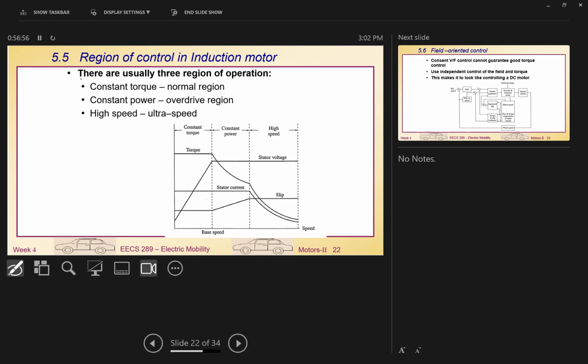And then I'm also given this region called the high speed region. When the motor goes into this space and goes further up, what's going to happen is that you are using this high speed performance. In this case, the motor voltage is still unchanged, but we start to weaken the current and the flux together to allow the speed to go one step further higher.